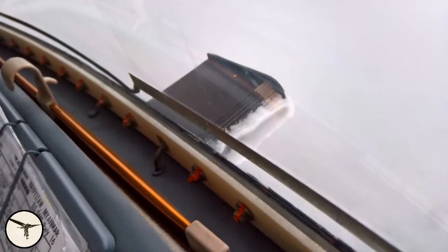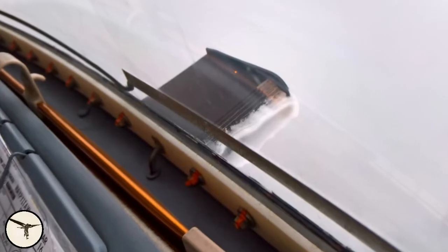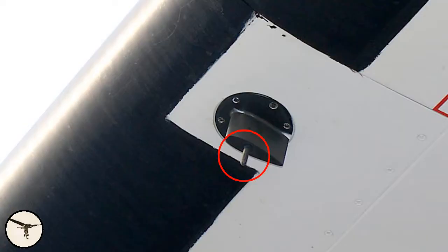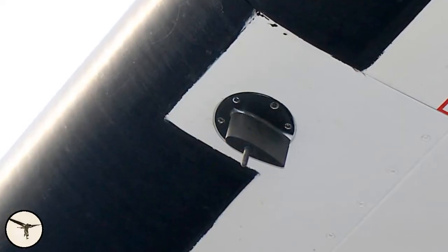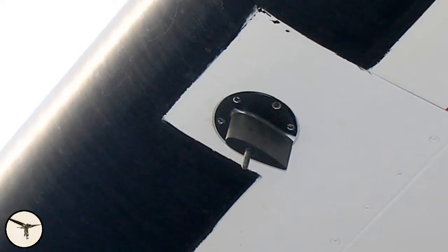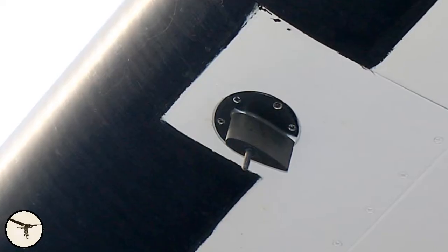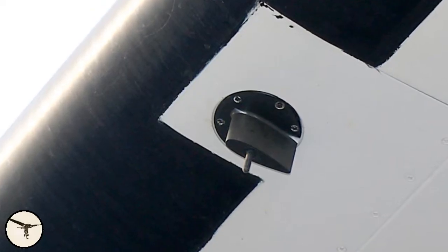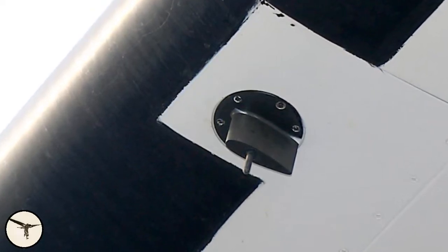When watching the ice evidence probe from above, you may not notice that this might be horn ice. To be sure, you have to lean forward and have a look. Under the left wing there is an electronic ice detector. It's a small probe that vibrates with a constant frequency. When ice forms on the probe, as little as half a millimeter is enough, the weight of the ice causes the probe to vibrate at a different frequency. This triggers an icing alert in the cockpit.